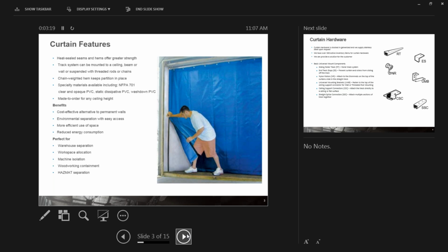One of the main highlights we're going to discuss is NFPA 701, basically stating that the majority of materials we're using on this are flame retardant. How that works is that the material is put inside a testing lab, where it is held up to a flame, and as long as the flame extinguishes within 2 minutes or does not continue to smolder once it hits the testing floor, we can generally be listed as fire retardant. I do want to highlight the retardant portion: I'm not saying that this is necessarily a fireproof system. We are dealing with vinyl curtains here.